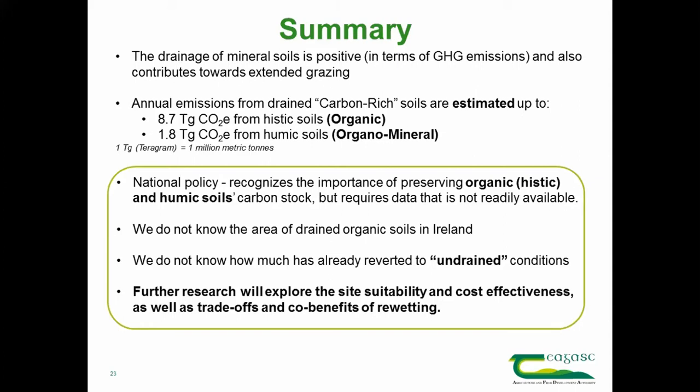We do not know how much has reverted to undrained conditions. So this is a very important point to make: if a drainage system was installed in an organic soil 20 years ago, or 15 years ago, or 30 years ago, the chances of that still maintaining a controlled water table... every drainage system has a limited lifespan, and no matter how much is invested in getting it installed, it does tend to revert back in time, and in some soils it reverts back a lot quicker than others.